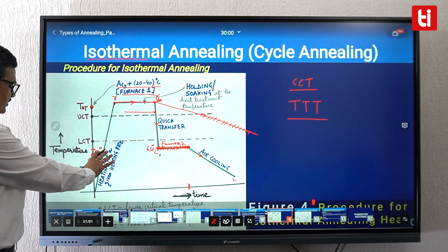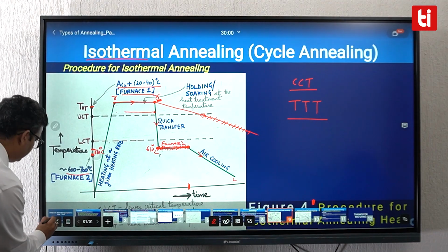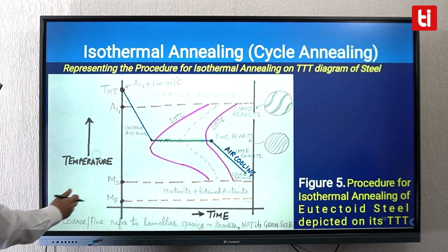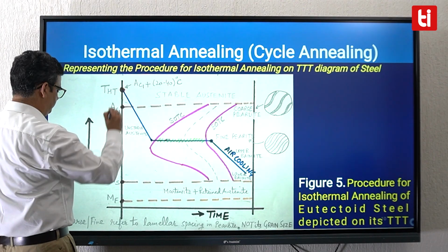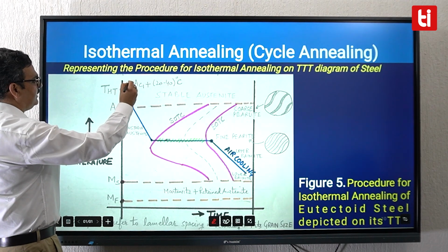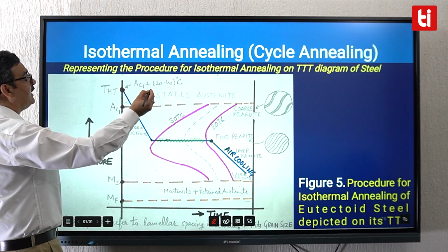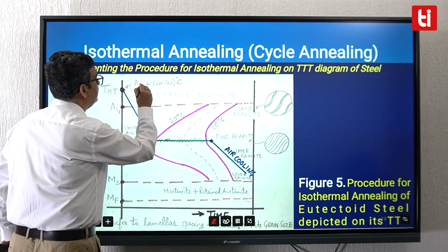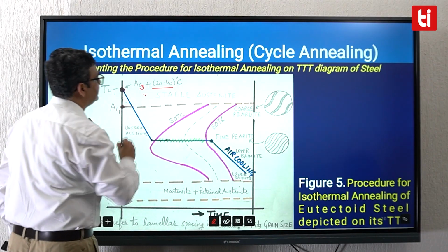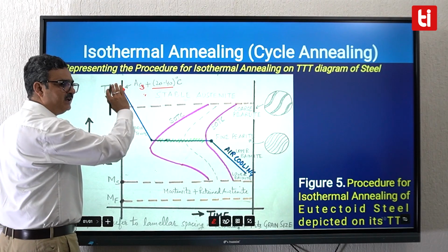तो अगर यही बिल्कुल चीज़ अब मैं आपको ट्रिपल टी डायग्राम की सहायता से दिखाना चाहूँ, so I have brought that diagram also for you. So you can see, you took the steel to this temperature, this is the heat treatment temperature and the isothermal annealing temperature. और ये टेम्परेचर क्या है, it has to be, OK, if it is for a eutectoid steel or a hypoeutectoid steel or eutectoid steel, this is upper critical temperature, sorry, AC3 plus 20 to 40 degrees in excess of it.